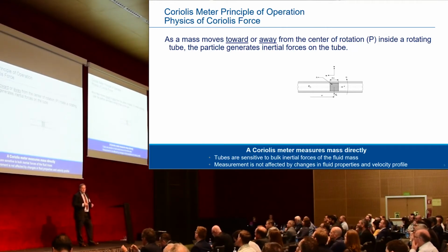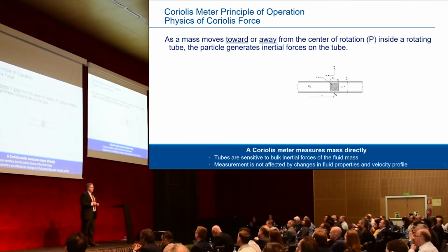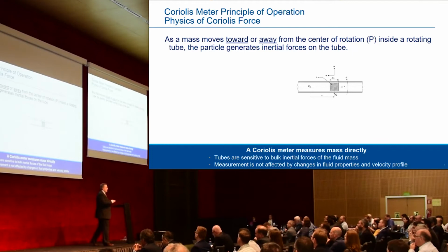I'm sure many people already understood this, but it's important to understand how we measure mass flow directly and why what I'm going to tell you later about being able to calibrate for gas measurement with either liquid or gas is true. It's because it's the force that's created that we're measuring. And that force can be created by molecules in any phase. It's a similar force because it's not related to the phase of the fluid or the density of the fluid.